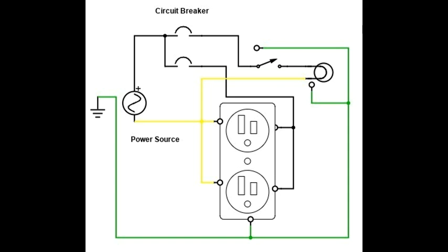So looking at this circuit, the black wires are hot, white or neutral, and green is ground. And shown are 2 circuits protected by circuit breakers. One circuit is for the light controlled by a switch, and the other is for an outlet, but they both go through a circuit breaker to protect that circuit. The hot wire, or the black, connects to the load. It's also the line which is switched. The neutral wire is the return. The ground wire is for safety and protects you against a short of the hot or neutral lines to a metal appliance. Remember, electricity follows the path of least resistance. You never want to be the path of least resistance.